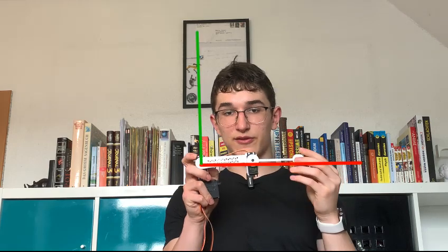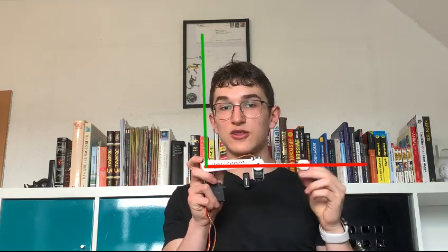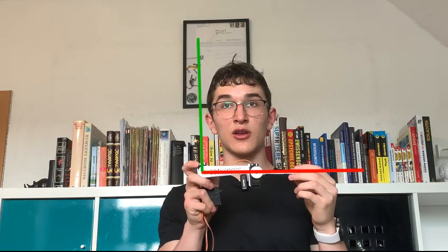For this, since the link lengths are 11 centimeters, as you can see here, for both of them, the maximum distance would be 22 centimeters since we have two link lengths. So to simplify even further, let's say the Y just doesn't change. It's just on 22, 0. The point is on 22, 0. So we go 22 units to the X direction and 0 units to the Y direction. As you can see, that's easy.